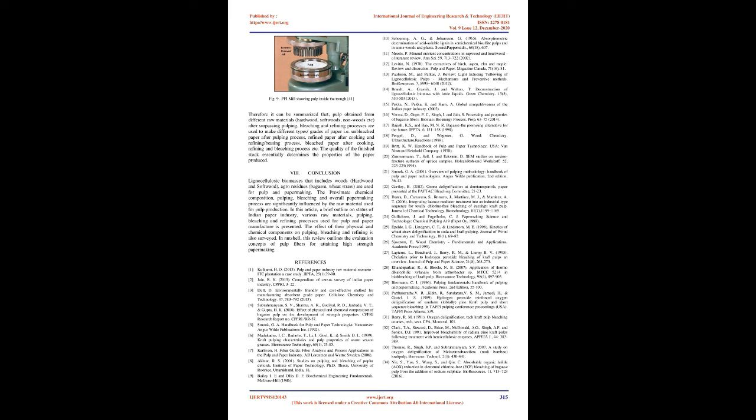37. To compensate for the lack of chlorine dioxide, TCF will either add higher dosages of peroxide, or supplement the process with ozone. TCF's problems with lower brightness potential, weaker fiber strength, lower yield, and higher energy requirements have eroded its promise as a successor to ECF. The ECF pulps constituted 93% of the world share of bleached chemical pulp market.